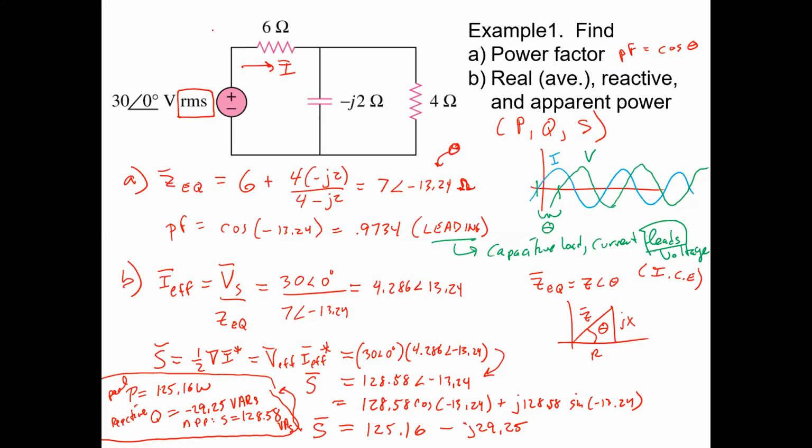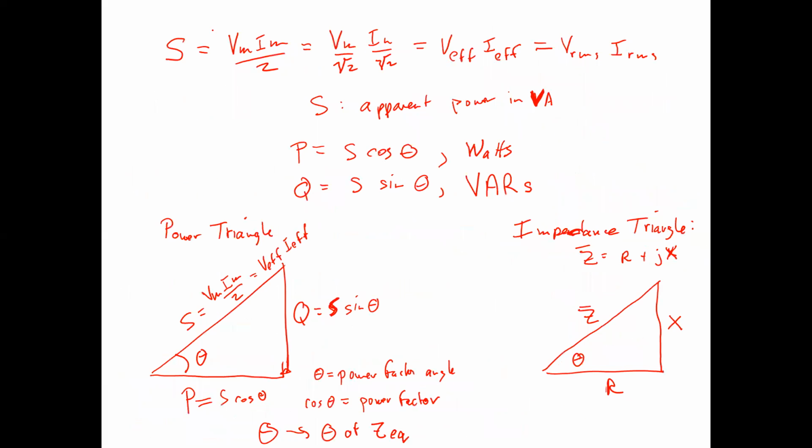So the power factor, we're going to talk about that when we do load balancing. What the power factor represents is the percentage of the power that you're actually using. So it's a percentage. I'm glad you asked that. I should have said that. You're getting this apparent power from the power company, but what you're actually using, converting into usable actual work, essentially, is the average power. And the power factor is how efficient you are, essentially, with the power you're given. I should have mentioned that. That's an important concept. We're going to look at that more tomorrow.